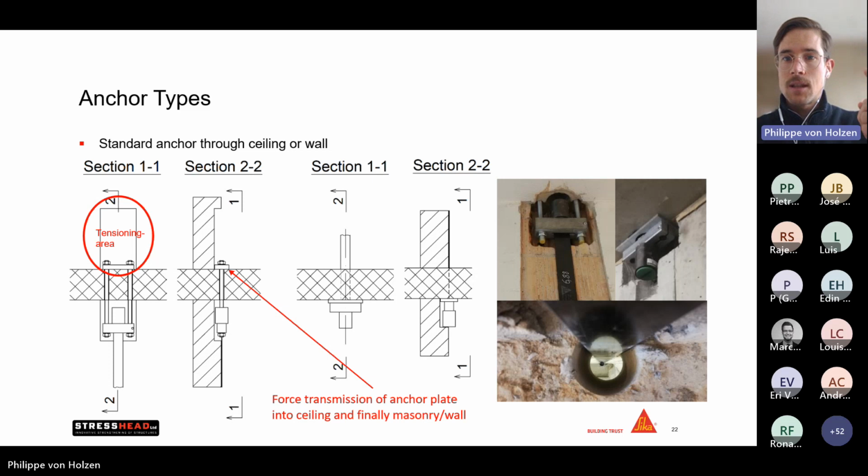We can pass the tendon through those perforations and finally post-tension the building over the full height with one single plate. And a new advantage here is that the system is so lightweight, we don't require any heavy machinery, whether for the installation or afterwards for the tensioning process itself, which most of the time we don't have access or the possibility to work with.